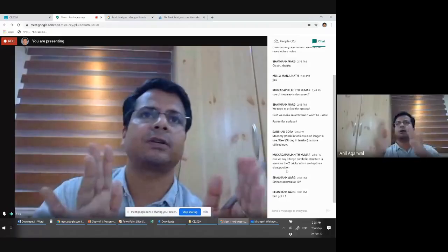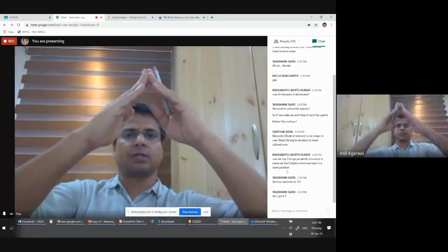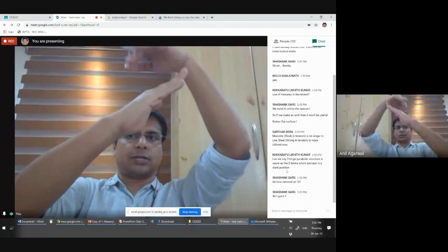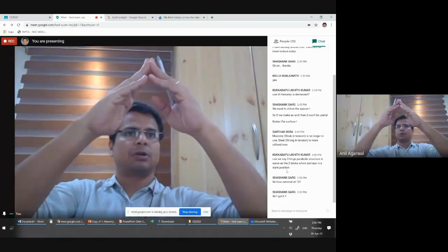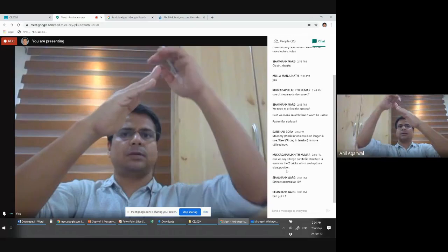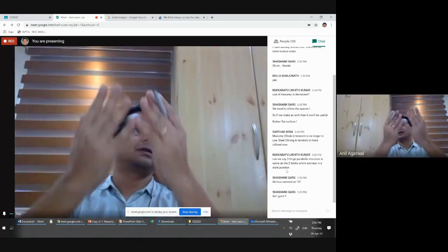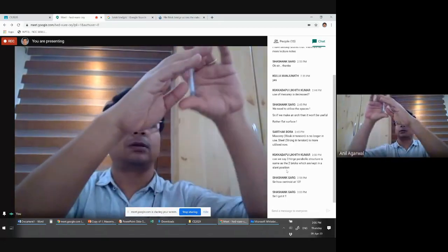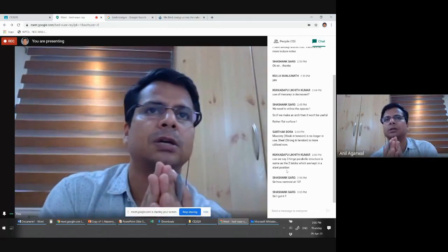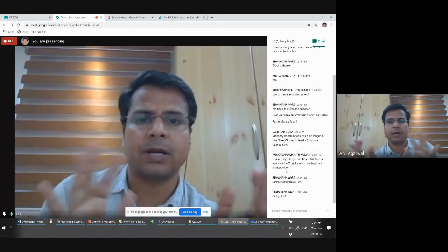The bricks which were kept in a slant position were a completely different problem. What was happening there was that these two bricks were there, and as long as you did not have any loads acting here, the system behaved in complete compression. But in reality you would always have some forces acting here. So these bricks were actually in flexure, carrying moment, so they were not really truly behaving as arches. But anyway, they were an approximation.